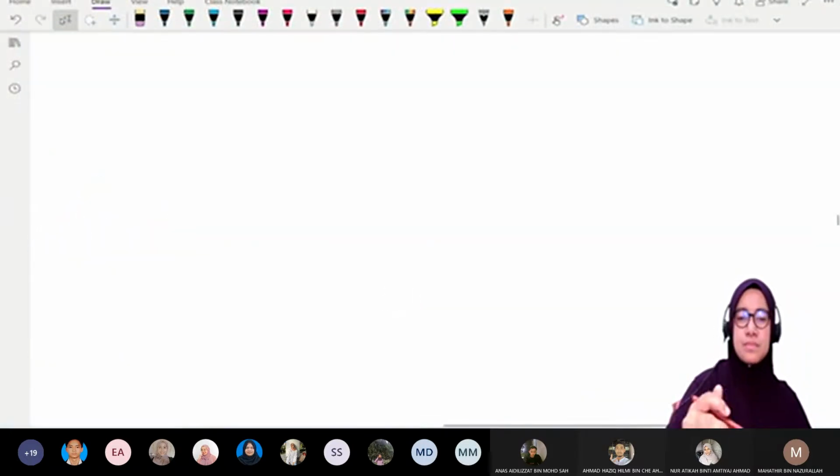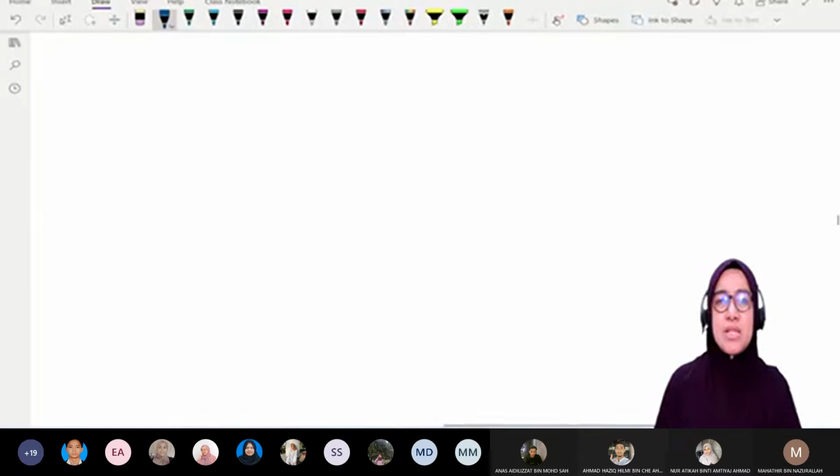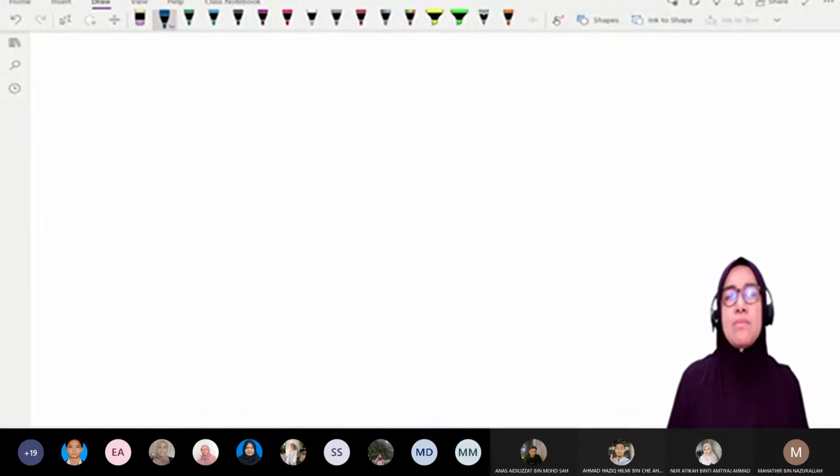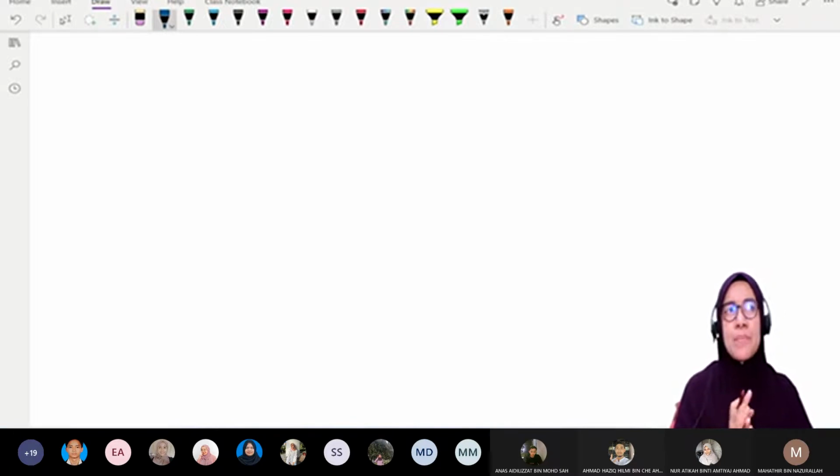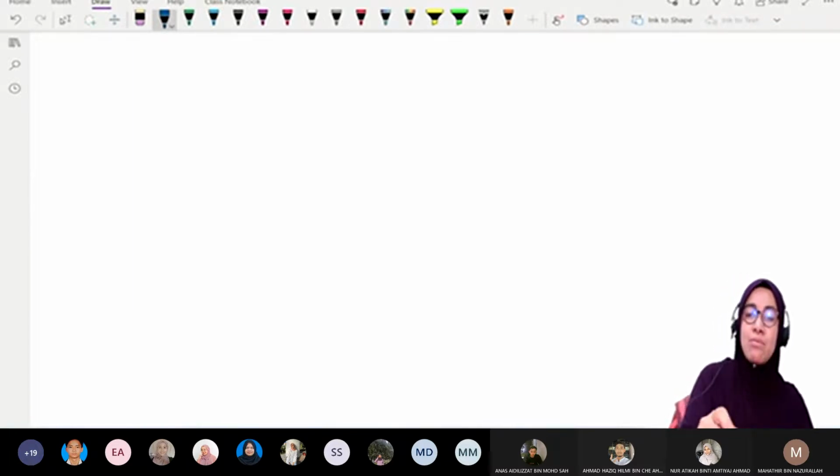Okay. So that is why understanding the concept of joint moment and member end moment is very, very important. Yesterday I showed you in the diagram that, beside member end moment, which we assume as positive sign convention, member end moments are all positive, clockwise. And we have another one called joint moment, and joint moment is always opposite to member end moment.